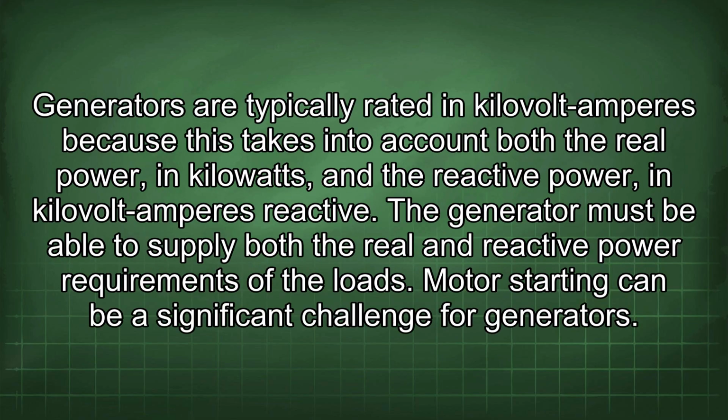Generators are typically rated in kilovolt amperes because this takes into account both the real power in kilowatts and the reactive power in kilovolt amperes reactive. The generator must be able to supply both the real and reactive power requirements of the loads.